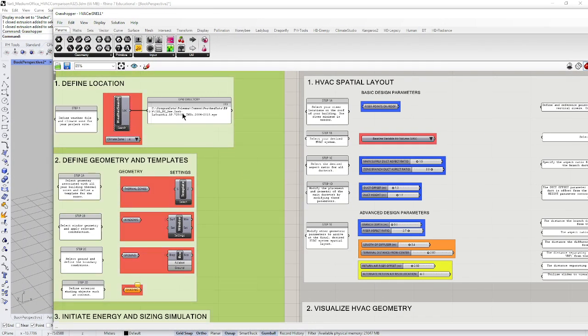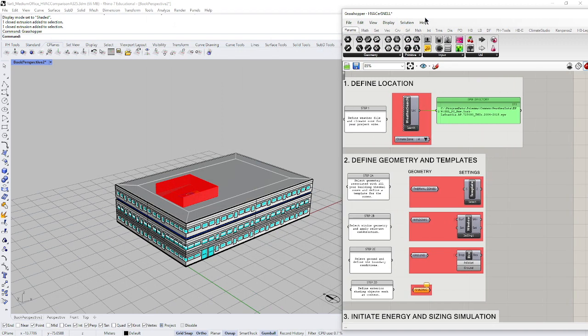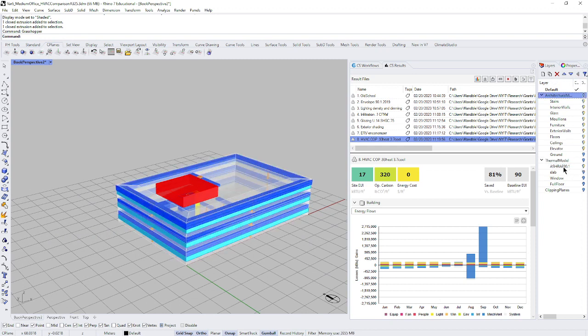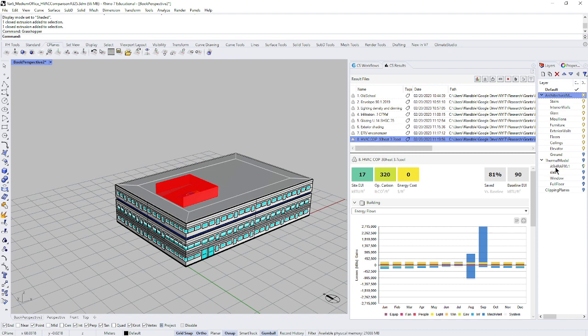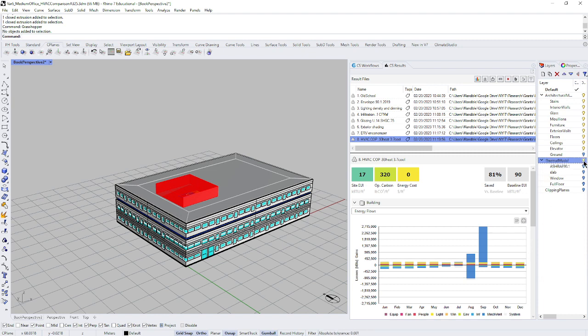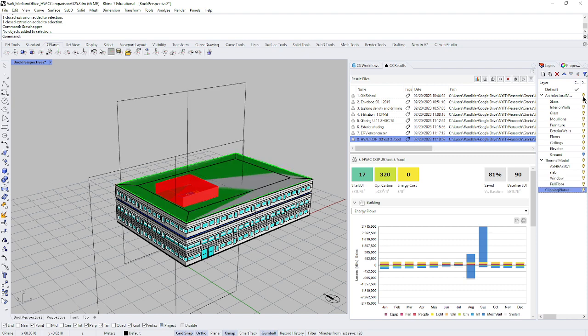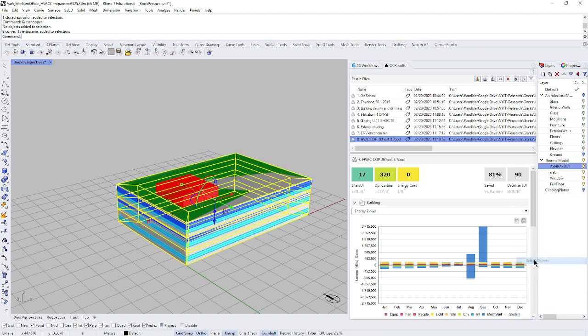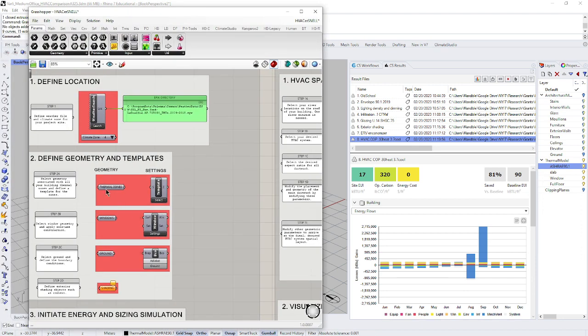I thought I'd canceled it, but I guess I hadn't. So basically, I have to go through these steps. I have to define my location, with some climate data like we've already been using. I have a climate zone. I then identify my thermal zones and my windows, and I can do that easily. I'll turn all this off, and I select my objects. Let me turn this on. Sorry, let me get this clearer. Turn off green panes. Okay, so I'm going to select these zones and attach them to this coding module here.